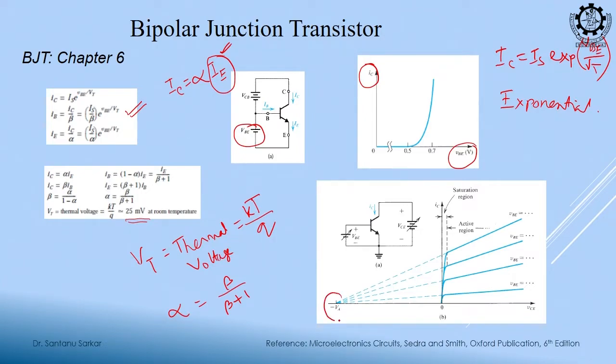Now, this expression you also know, what is this? Early voltage. How is this formed, or what is the explanation for why this is happening? Base width modulation, right. Effective base width is decreasing. You understand that? See, ideally this current should be flat, right. Here what is happening? Collector potential is increasing. So if collector potential is increasing, the collector and base junction becomes reverse biased, right.